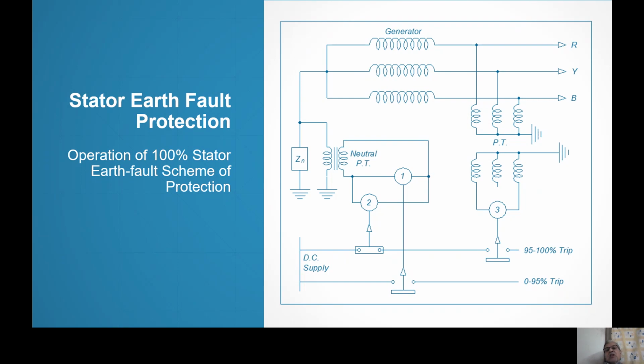Then why at all should you sense the neutral fault, neutral earth fault? Neutral earth fault we should sense because neutral earth fault is also very dangerous. Not neutral earth fault itself, but if second earth fault occurs after some time, maybe after 1 month, whatever, then your neutral due to first earth fault is now solidly grounded, and therefore second earth fault will lead to very high current through the generator stator core and very bad damage, very costly damage. Costly damage to the generator repairing also, and costly damage with reference to revenue also.